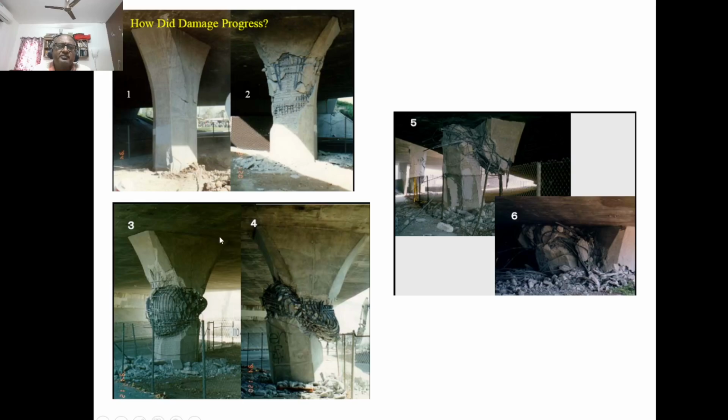So that means it has not failed at the top due to anything, but you are creating a zone of failure here, which is again a shear failure. Even though theoretically it looks like everything is fine, you are increasing the size at the top, so you are much better for the bending moment diagram and shear force diagram. That is the way we think. But we have issues like this, where we fail.